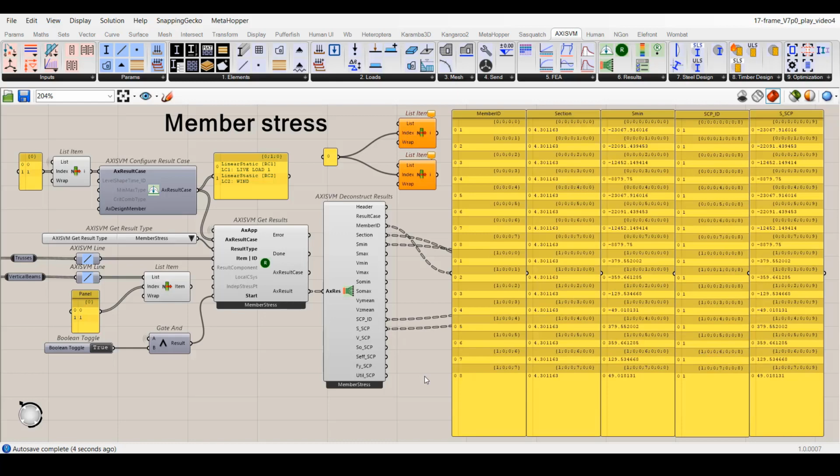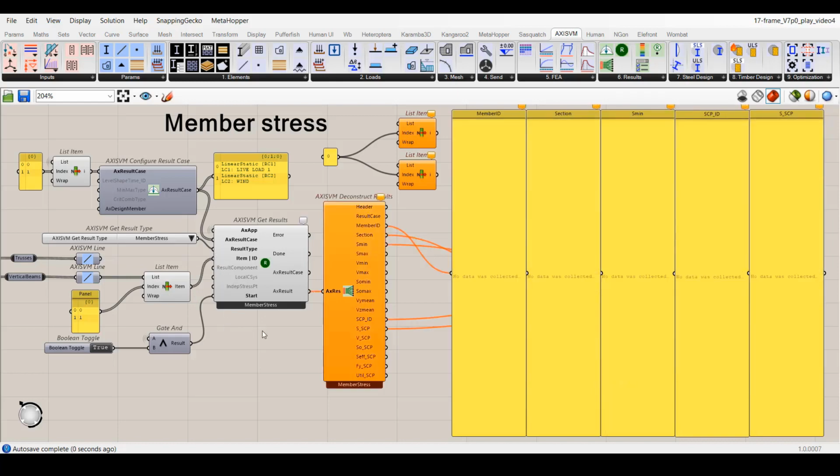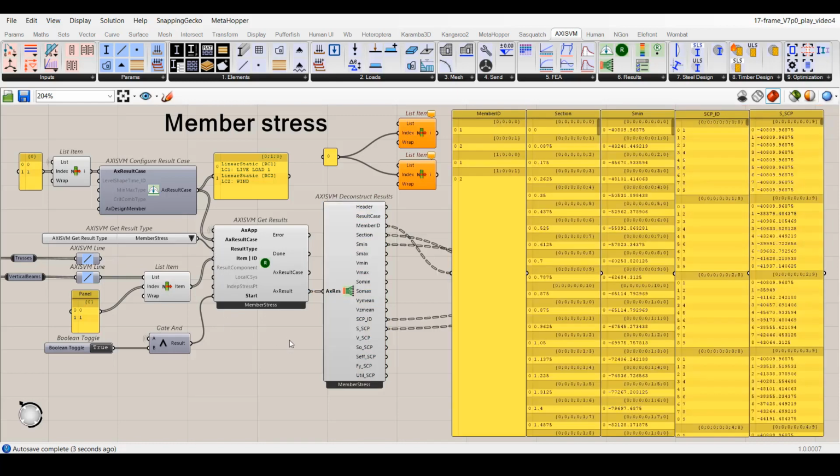Currently, we see the results for a truss member, that's why it's very clear and simple. One section and one stress calculation point per section belongs to each member. If I change the input to beam structural members, the data contents of the panels are quite different. Here you can see that, for example, 9 stress calculation points belong to the section number 0.